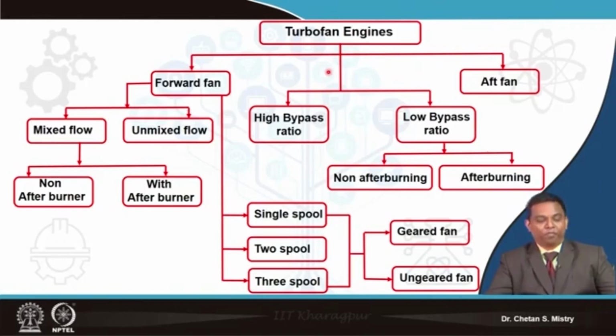Okay, this forward fan may be of mixed flow configuration or unmixed flow configuration. This mixed flow configuration can further be accommodated with an afterburner, so it's with afterburner or without afterburner. This forward fan can also have a single spool configuration, 2 spool configuration, or 3 spool configuration.